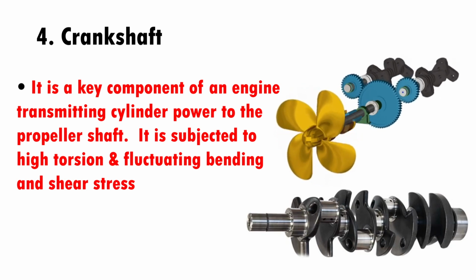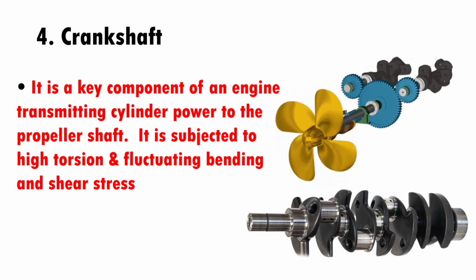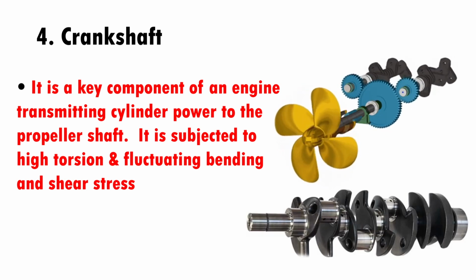Crankshaft. It is a key component of an engine transmitting cylinder power to the propeller shaft. It is subjected to high torsion and fluctuating bending and shear stress.